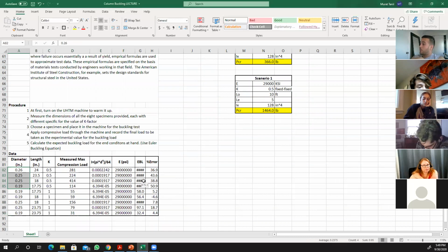If I increase the diameter, is it gonna increase the peak critical load or decrease? What is my gain, etc. And the length, how length affects the column capacity when it comes to buckling, and different connection types.